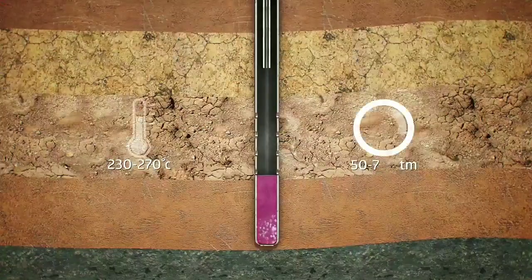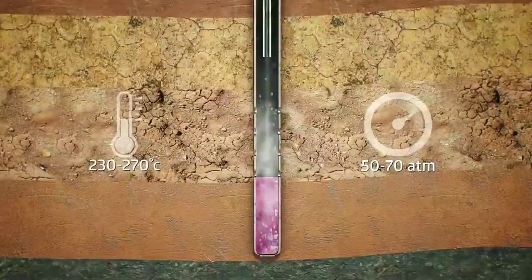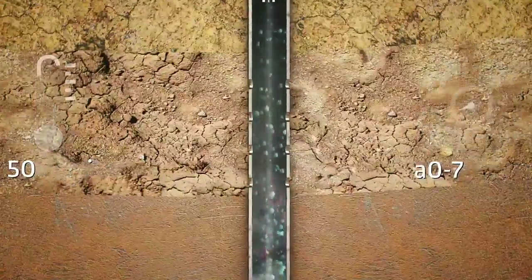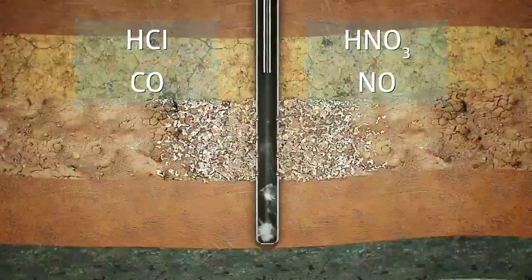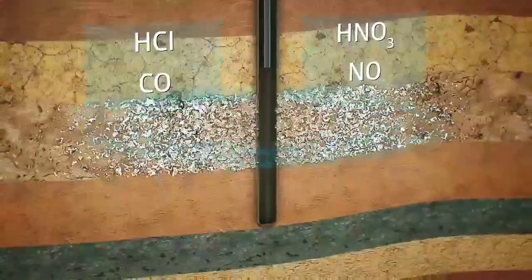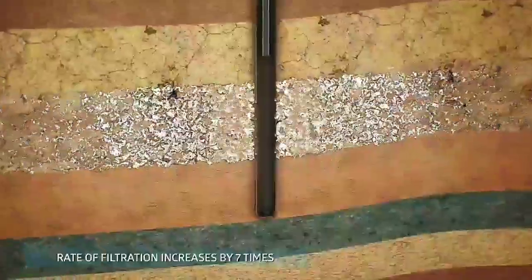After mixing of compounds number 1 and number 2, the pressure and temperature increases. Main thermodynamic potential of the system occurs in the formation and not in the production casing. Gas generation process begins. The mixture of gases is filtered into the formation in presence of hydrogen. The affected area of the thermobarochemical processes can be up to 80 meters and more. The rate of filtration increases by 7 times.